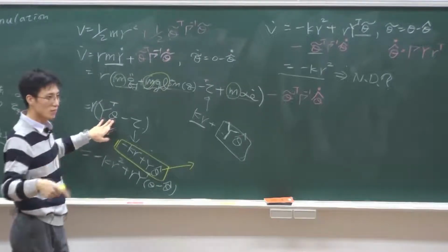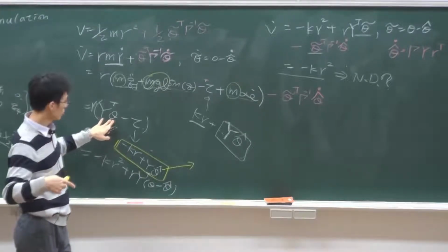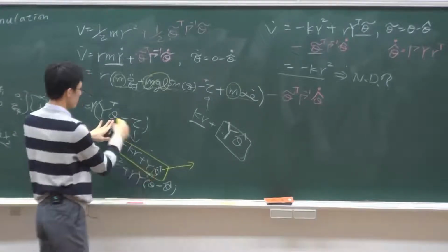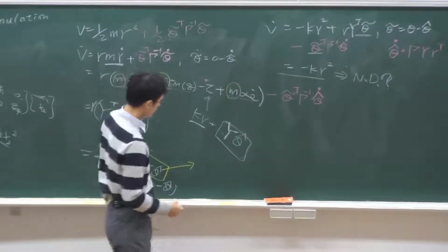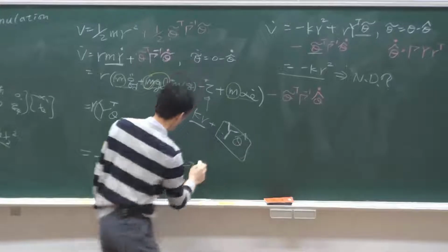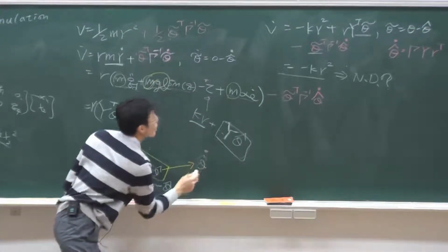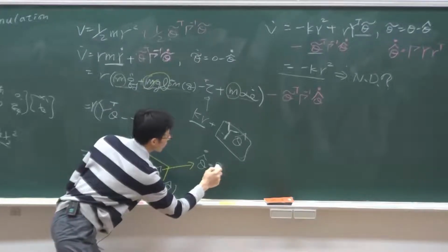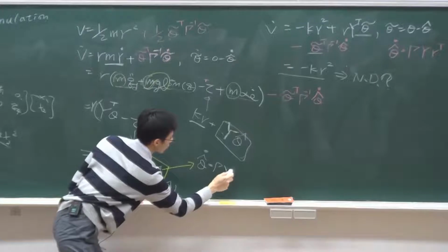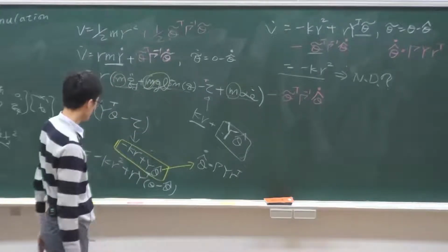And because it's an estimate, you need to learn how theta hat can approximate theta. And the learning algorithm is this. Theta hat follows the dynamics: theta hat dot is equal to gamma, which is the control gain, y r transpose. Okay.